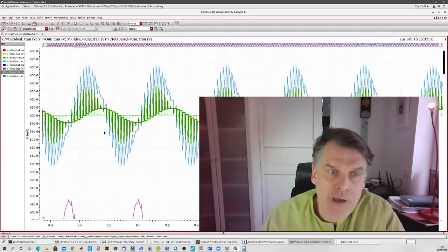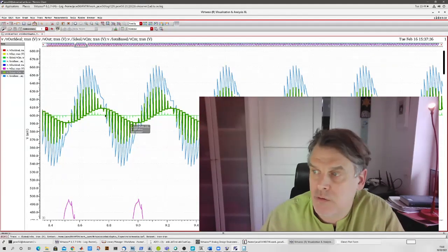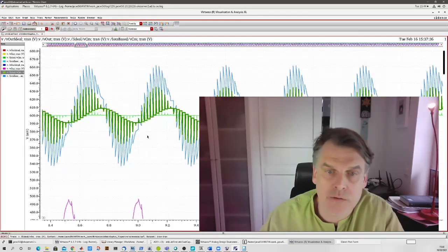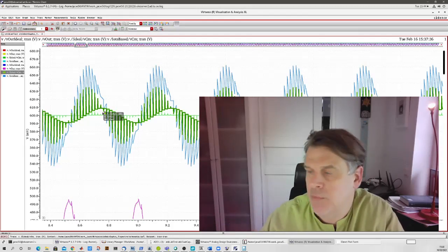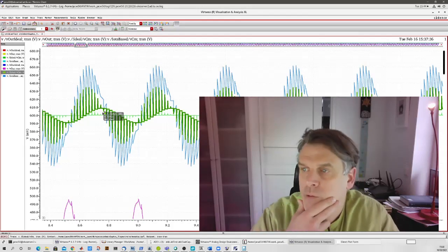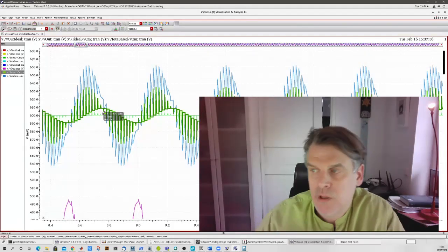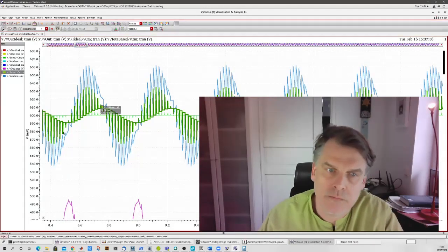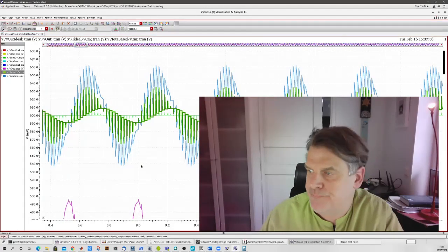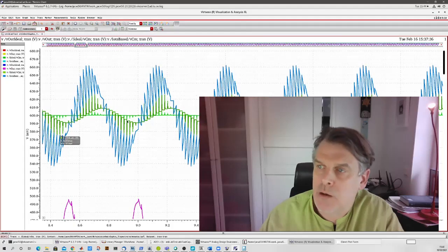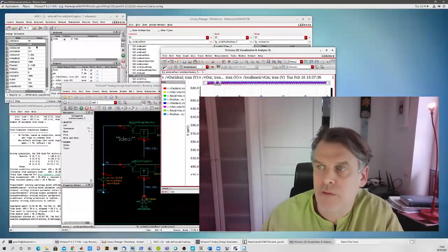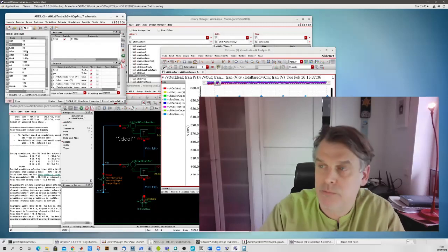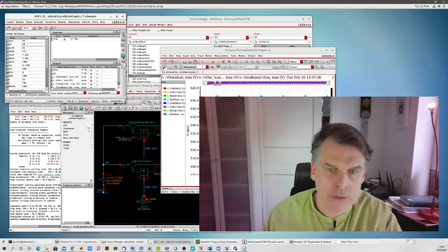So here we have a pretty good explanation for parts of it. We see the green one fluctuates by 20 millivolts or 10 millivolts up, and the signal swing was 100 millivolts or 200 millivolts maybe. So there is something related to the gain there. That probably explains some of your op-amp limitations, etc. You can also set the pole frequency to a much lower value, etc.